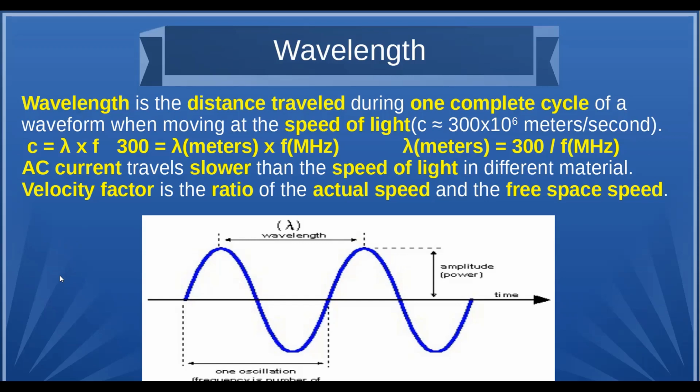There's another formula, which I didn't put on here. Use 468 divided by the wavelength times the frequency, or use those. And the answer comes out in inches because they've already factored the conversion factor in there, and it gives you inches for half a wavelength, which is another one that's commonly used.